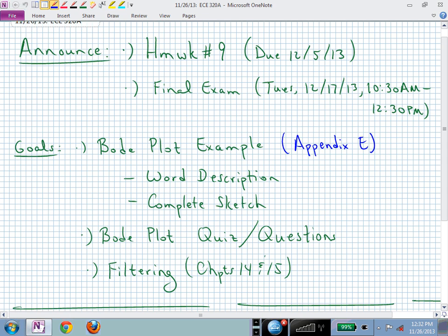And the filters that we should be comfortable with are low pass, high pass, band pass, and band reject. Those shapes we should be comfortable with, and you actually should be able to build those up on, let's say, a frequency response diagram. Now you can extract from that the transfer function. So you could do filter design based on what we've talked about, especially after today's class.